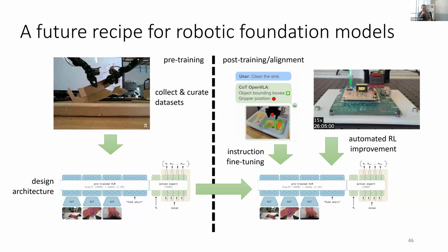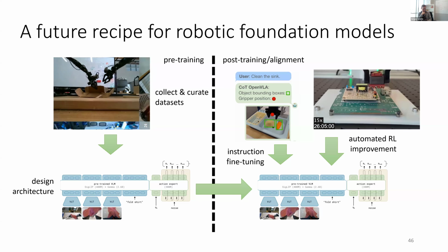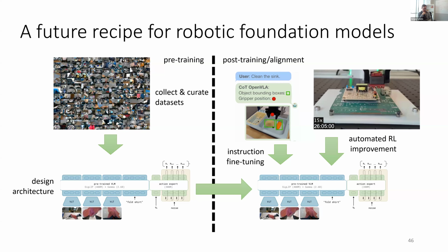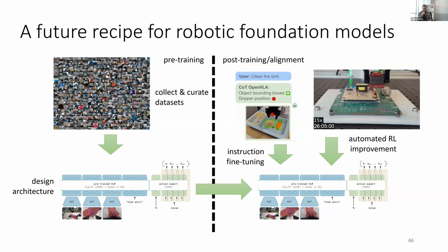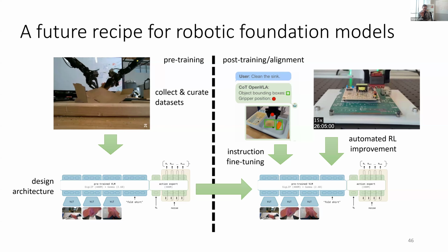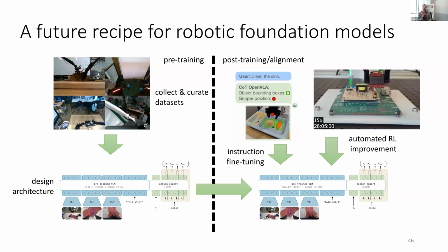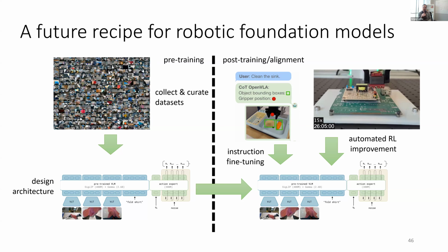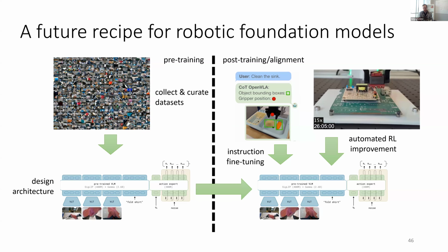For the motherboard demo, this was a demo that Charles and Jianlan put together for the human-in-the-loop SERL paper. There is no explicit pose estimation. There's actually no force sensing. There is a little bit of cleverness for the low-level controller on the robot, purely for the purpose of not damaging the motherboard. Jianlan did quite a bit of careful engineering to essentially clip the motor torques so that the robot doesn't apply large forces on contact. That's important in the practice phase, because if you're going to be touching sensitive electronics components, you need to do that right.